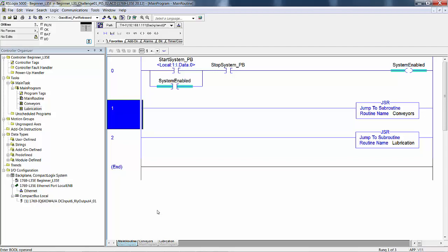If you know the surface speed of your conveyor, and you know the length of the conveyor, then you can create logic that determines once it sees the leading edge of the carton, after a certain length of time, the leading edge is going to be at a certain distance from the entrance based on the speed of the conveyor belt and the elapsed time. Just something for you to think about. When you get done with this manual, you could go in and play around with that.